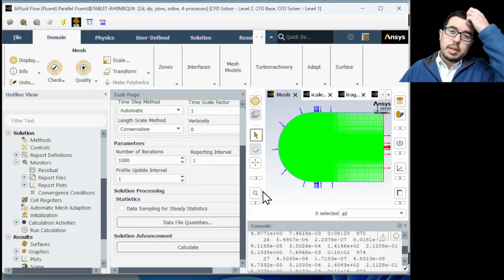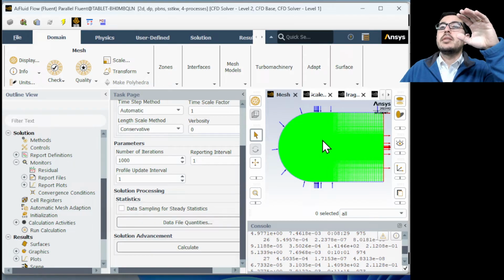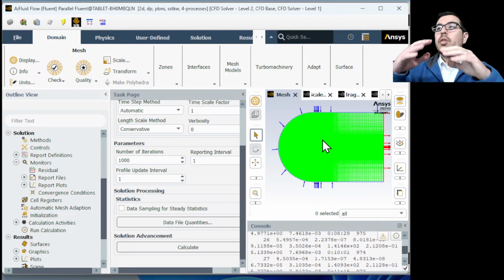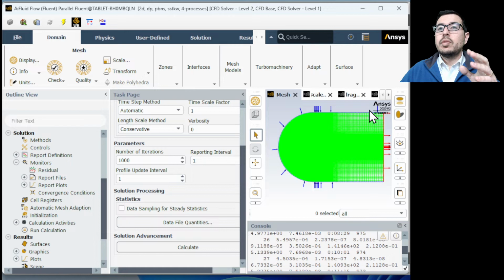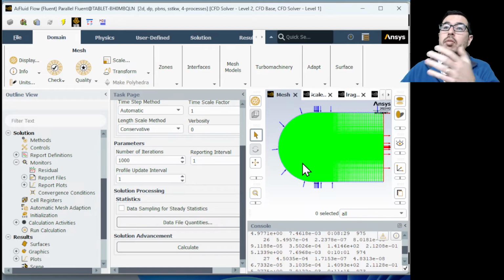The first thing here is to note that we don't want to remesh and rotate that airfoil relative to the boundaries that we've set up. It's much easier to change the direction of the air flowing in or across this airfoil.